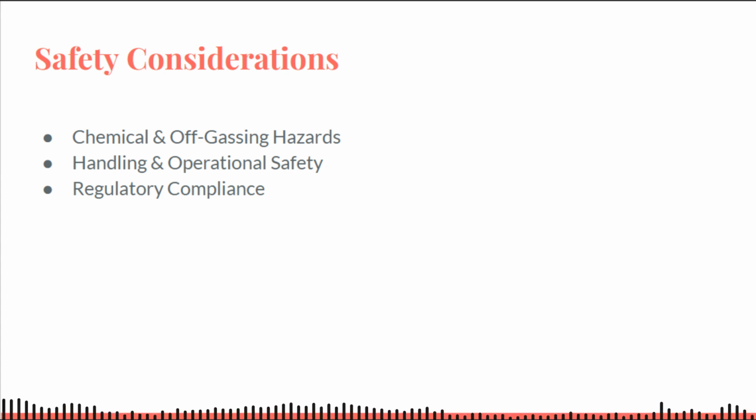For instance, CMP recommends an MDV if using their ozone AOP unit with a variable speed pump on very low speeds. The Reddit example of a homeowner noticing gurgling bubbles with a CMP AOP system highlights this. The CMP rep noted this air removal filter is available for those who prefer no bubbles in the pool. A properly tuned system, or slightly higher pump speed, and/or an MDV can eliminate that issue.